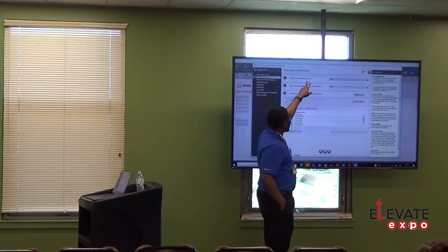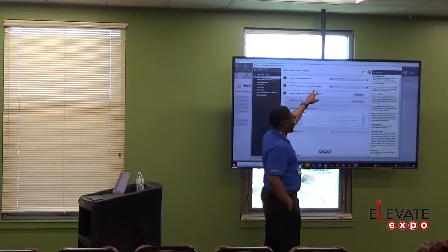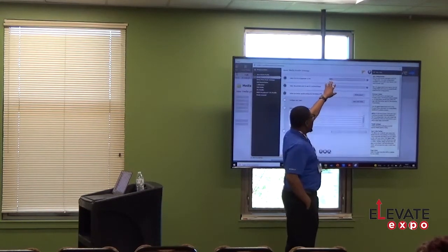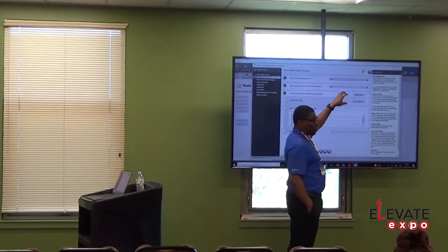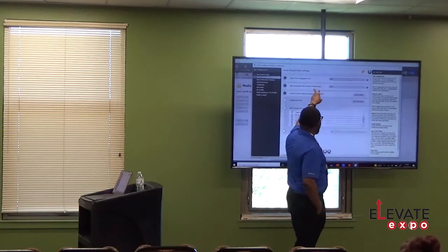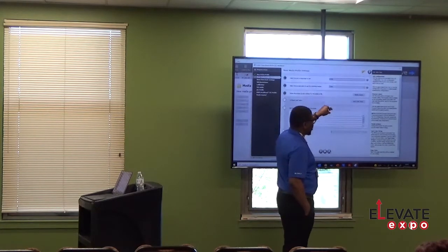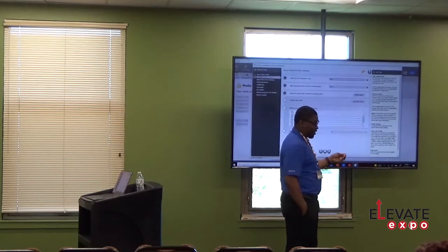The difference between saying what in configuration to use and where it says select the process colors to use for rendering images is this: in configuration, you're choosing what inks you're using to print on that specific media. Here, this one is not about what you're printing. Process colors is what colors should I reflect in this media profile.